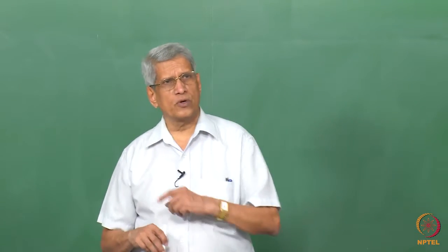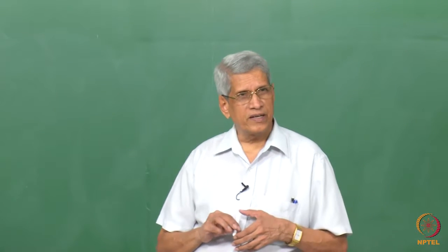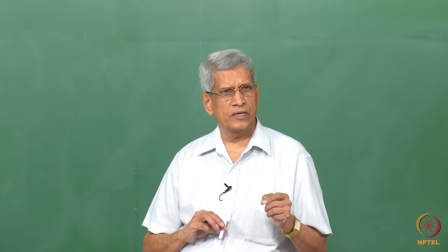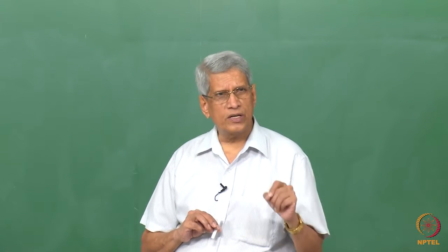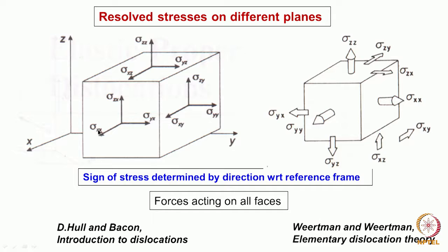Another aspect one has to be very careful about is that I have taken from two books how these stresses are defined. One has to be very careful about it, because different books follow different notation. In this particular one, the first letter represents the direction of the stress. The second letter represents the plane normal, which tells us the plane on which it is acting. So here, sigma y first represents that it is in the y direction.